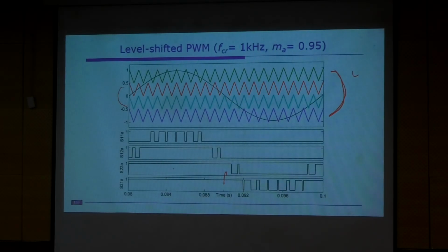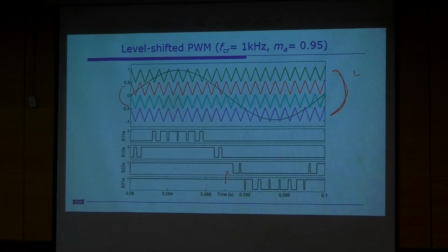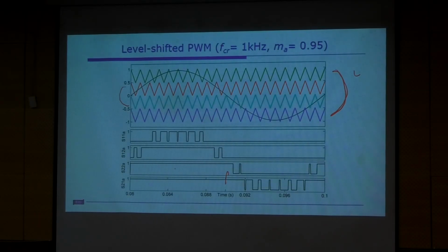So that is the drawback with low speed. For example, if a low speed operation is there, the output voltage itself is reduced, which means the number of levels is reduced. In case of electric vehicles, that problem is there, because we have variable speed, from low speed to high speed operation, with continuous change. But in industry, normally that much variation in speed will not be there. Most of the time we have constant speed operation or very little drooping. So based on the voltage you record, you will adjust that, right?